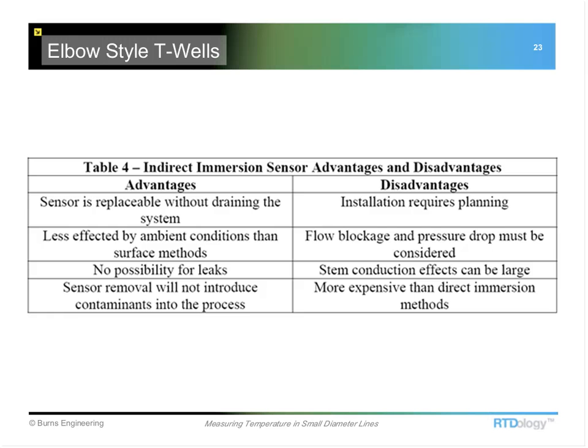Yeah, that's a good point. The thermowell applications typically can use a less expensive style sensor, just because there is no electropolish or high polish required as is required on a direct immersion style.